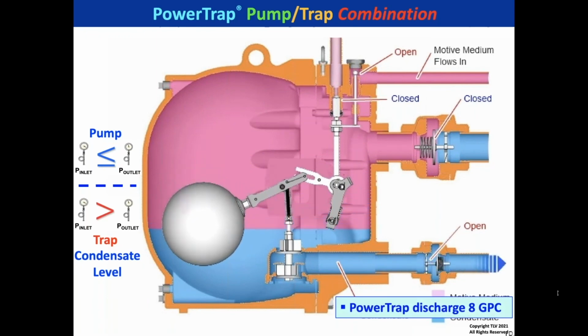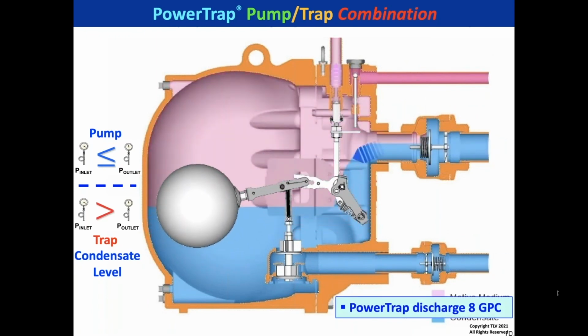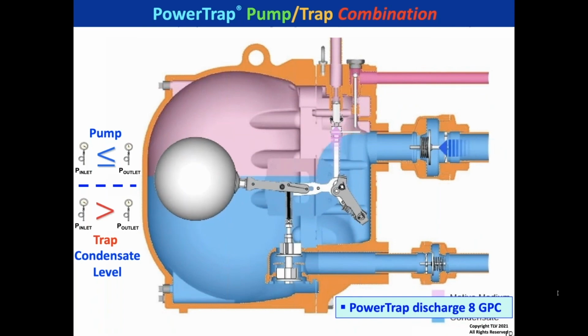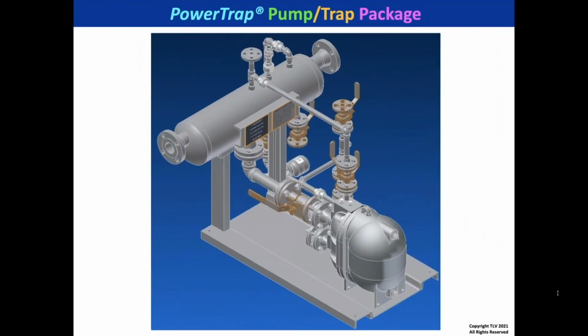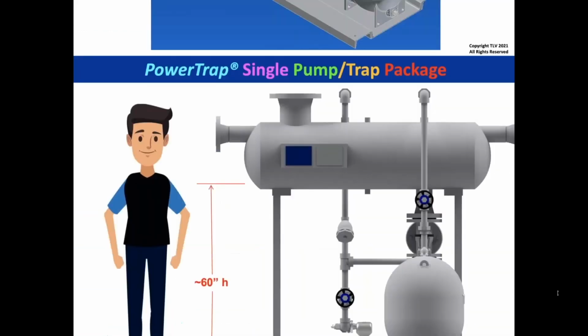Each cycle is about 8 gallons, and that's relatively consistent among manufacturers for 3x2 units. They go into a package unit that looks like this. The receiver that you see is actually not a receiver, it's a reservoir, it's closed. When they're open, we call them receivers. When it's closed, we call them reservoirs. This would be similar to a level pot.